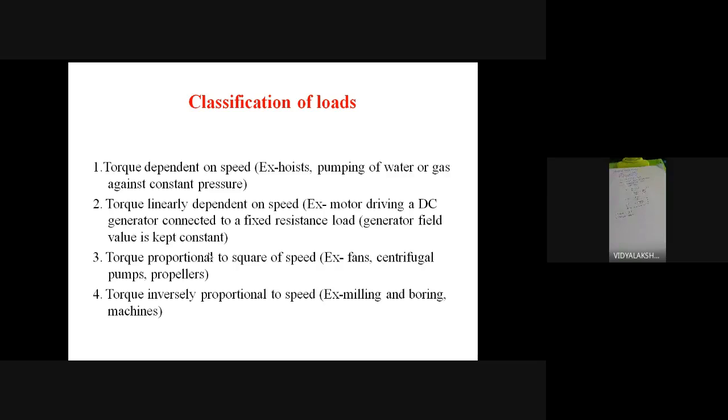The same way here, the active load torque, whenever the rotation may change, this type of load torque, whenever the position or rotation is changed, again it will come to the original position. It retains the sign. It won't change the sign. If it is my load torque, the particular load will be positive.